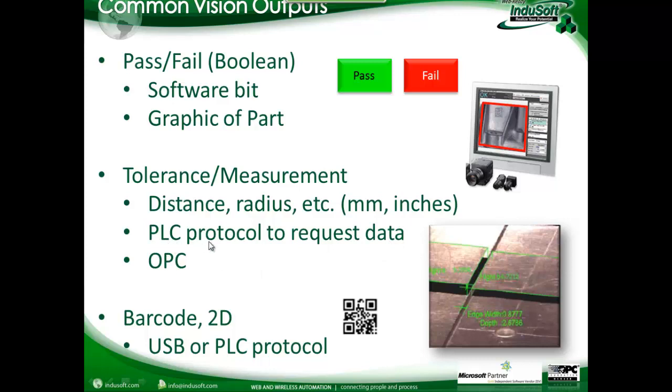That might come back in as a PLC protocol for InduSoft Web Studio to request data directly from the camera. Some vision systems might be connected to InduSoft Web Studio via a driver that we have, or OPC, and get the information directly out of that. Here's a screenshot of a vision system where you might see the depth and the measurement. It can detect the edges or the spacing between different things and give the actual measurements. Then you can keep track of those, either log them in a database, or if it just passed, send it on through and maybe you don't have to keep track of it.